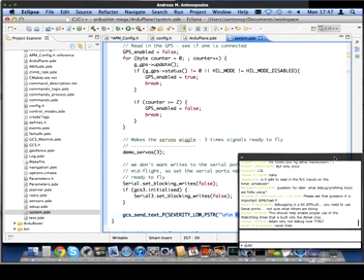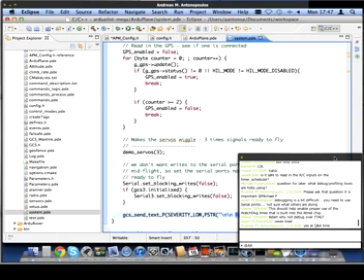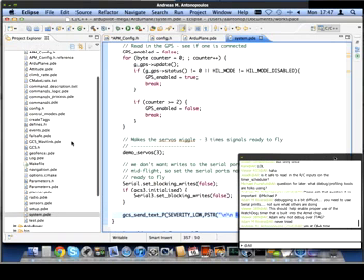Oh, and trimming the radio, getting the 0 settings for the trim from your transmitter, which again makes it important that your transmitter is turned on when you boot ArduPlane, because otherwise it'll get the wrong trim values, which would mean that it wouldn't fly very well once you take off. And finally, it says that it's ready to fly, and the main flight code takes over, and all of your hardware is initialized. So that's it on the main startup of ArduPlane.